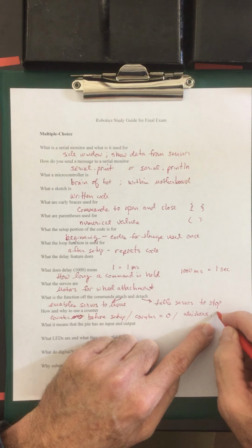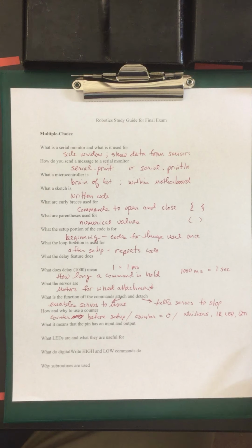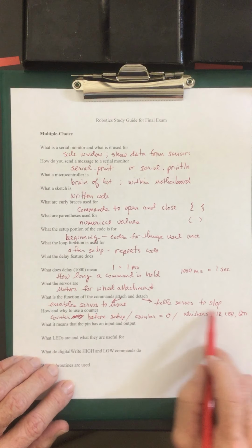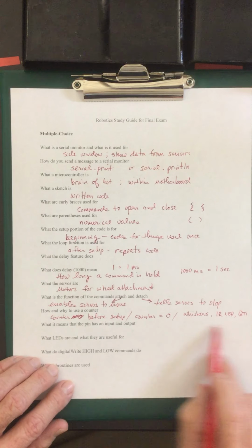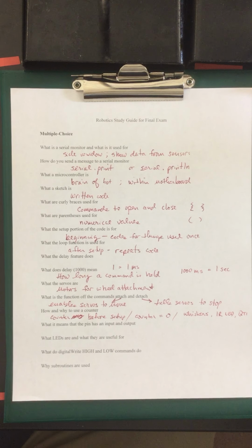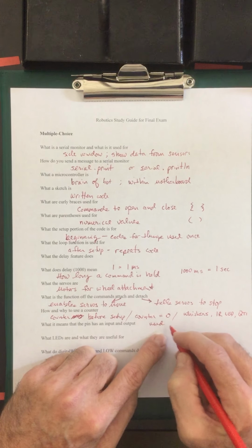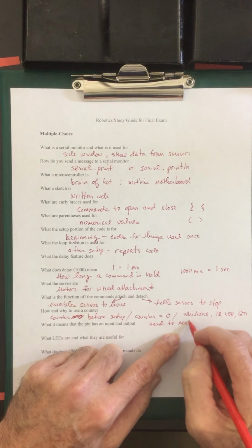If the IR LEDs detect an object, it can advance the counter. If the QTIs come up to an intersection, which is 1, 1, 1, 1, all black, you could then say, okay, I want to make a left-hand turn and advance the counter. So we establish the counter being equal to 0, and then we have something to sense. And when a condition is met, we advance the counter. So it's used to make decisions. That's what the counter is used for.